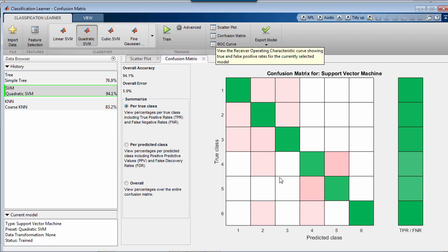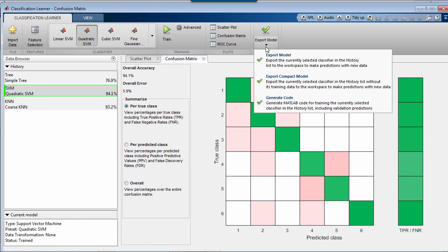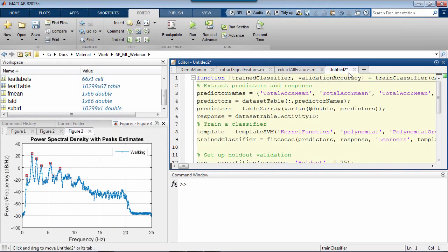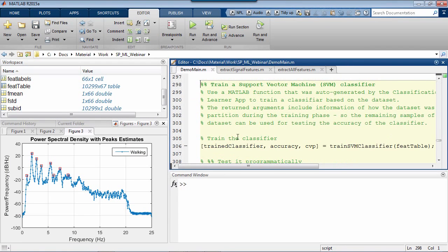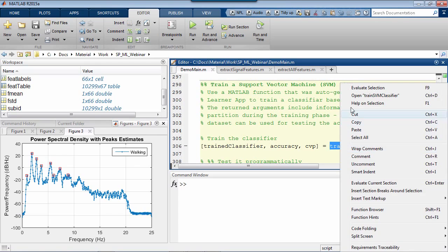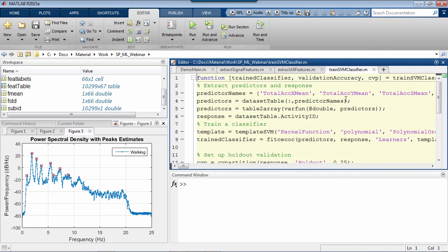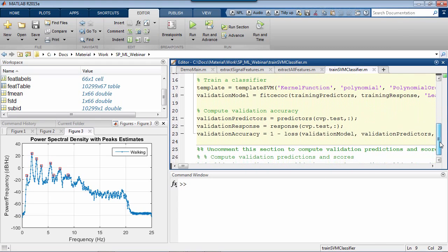As in many other cases with MATLAB apps, you can then turn your interactive exploratory work into a bit of code to automate the same steps programmatically. In our script, we're using a preset version that comes exactly from the same workflow. What's interesting here is a 3-line code pattern consisting in choosing the settings for the classifier, training it, note the fit keyword in here, and running it on new data to return the predicted class.